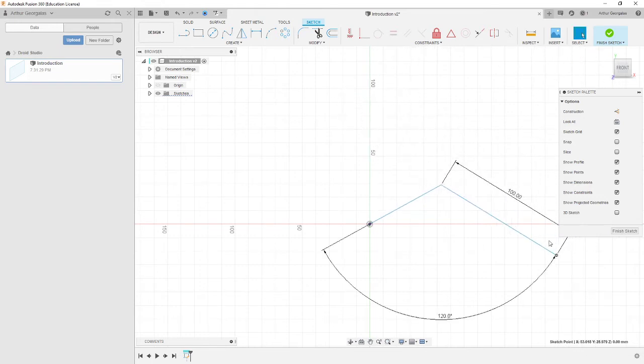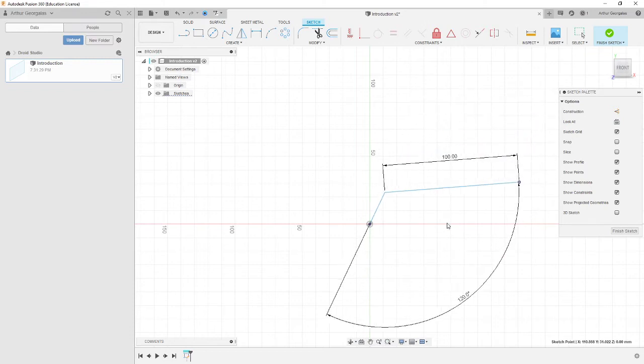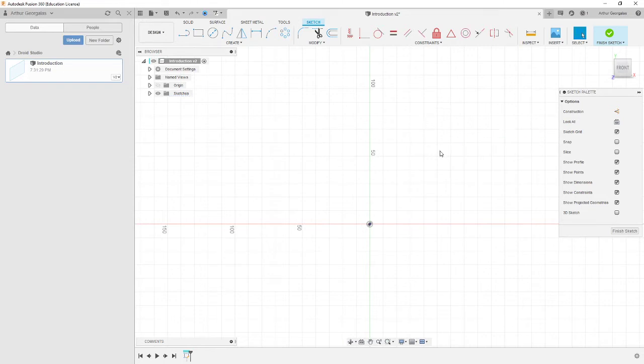Trying to move things around manually in a sketch, like SolidWorks, is a bit wonky at times, so everything should be controlled properly by dimensions. Again, if you need to use dimensions, which you should always use, press the D key or hit sketch dimensions.